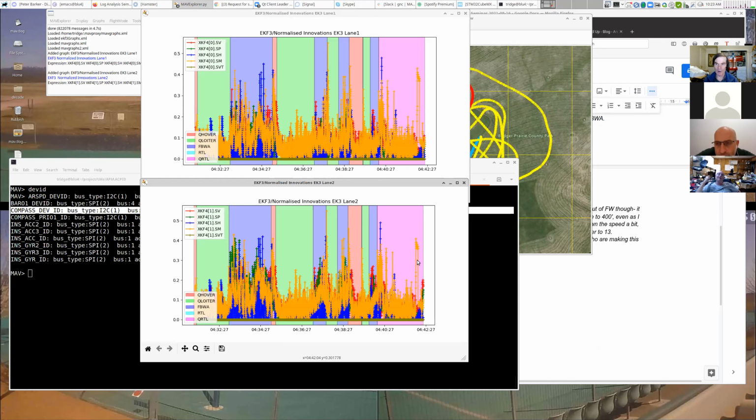Yes, they could be. And one of the things I wanted to add, Paul, was an EK3 primary parameter, so you could pick which is your primary IMU. Yes. And so it will lock on to, in my case, I want it to be the second IMU, so I'd set EK3 primary to 1. So I'm planning to do a PR for you to just have that. It should be a very simple patch to be able to select which one it locks onto at boot, rather than waiting for it to change IMU mid-flight.